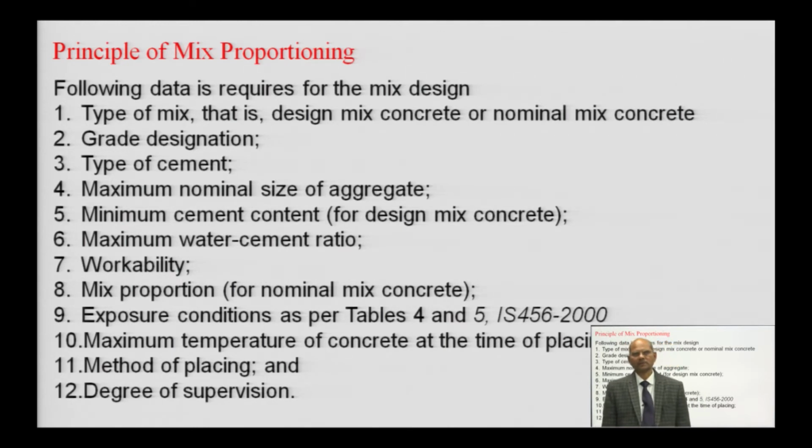If the water cement ratio is more, what will happen? There will be a durability problem. So, it depends on the environmental conditions and exposure conditions; we have to restrict the water cement ratio. It should not be more than that.